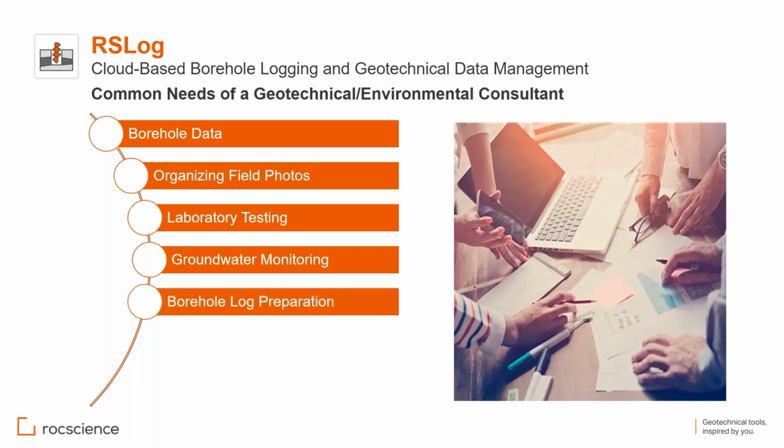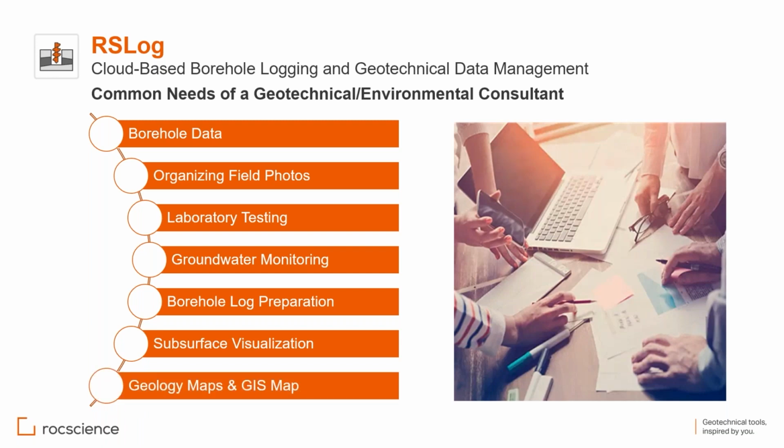And then you prepare borehole logs based on all of this data, and based on the borehole logs and stick logs, you want to go with subsurface visualization, designing the cross section. In the course of the project, you will need to have access to geology maps, and after a few years when you have several projects, you would like to have a GIS map. So these are essentially the basic needs of a consulting firm that deals with different types of geotechnical or environmental projects.